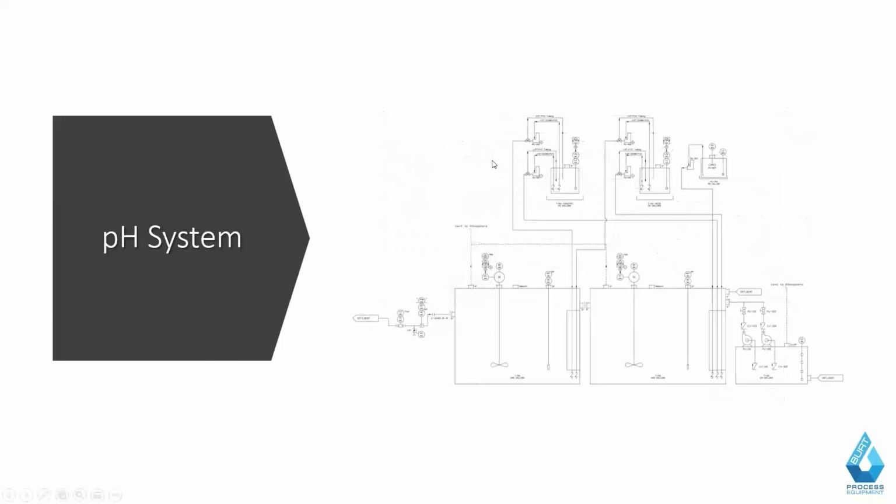And then from a P&ID standpoint, we have our 2 treatment tanks, our lift station flow and our gravity effluent flow. We have our bicarbonate addition, we have our acid and base addition, and then we have our final effluent flow and pH in those cases.